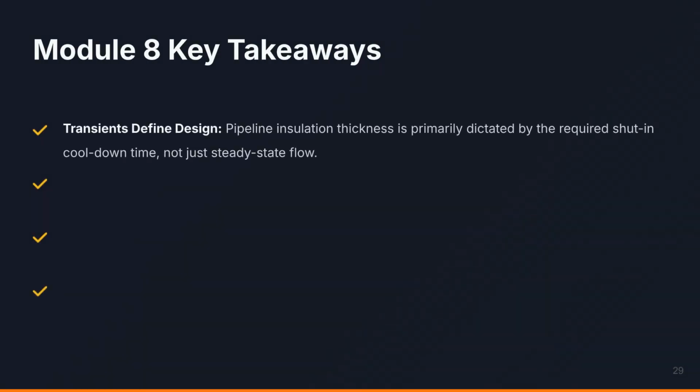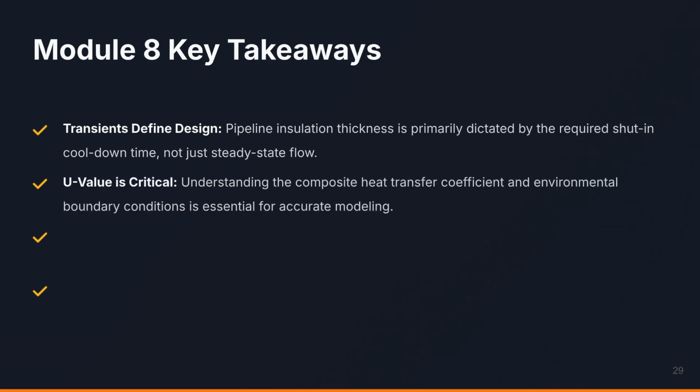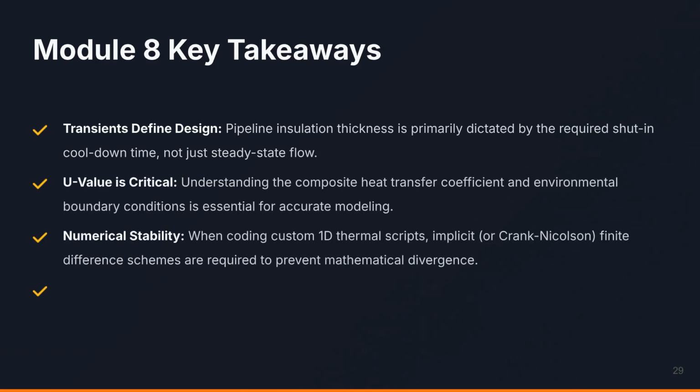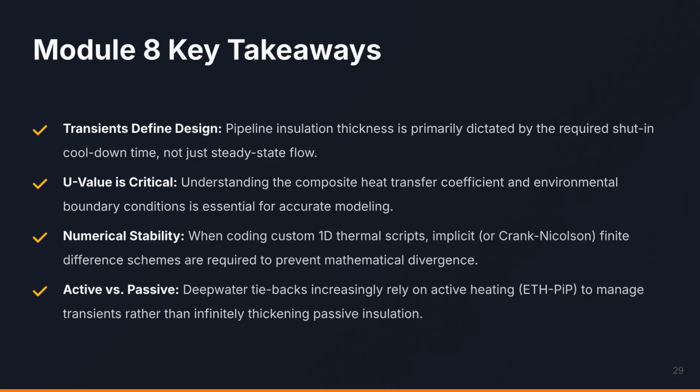To summarize, transients drive design, U-value calculations are vital, implicit solvers ensure stability, and active heating is becoming the preferred choice over excessive passive insulation in deep water.